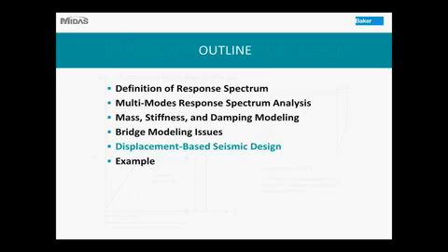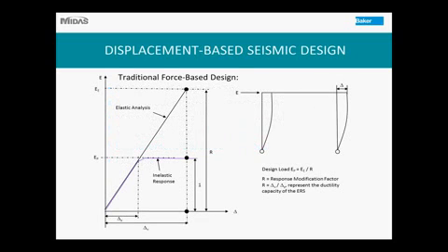And then let's talk about the concept of displacement-based seismic design. Traditionally, we're using force-based design. So you basically run your response spectrum analysis and get your elastic analysis, and divide the force readings from your elastic response spectrum analysis. For example, the base shear and the overturning moment read out from your model, and then you divide that by your response modification factor, the R factor here.